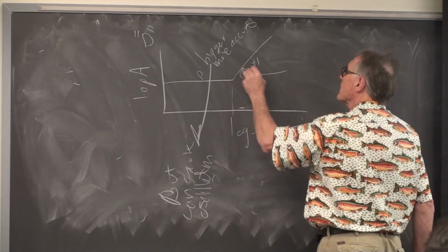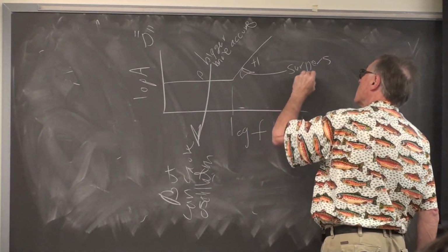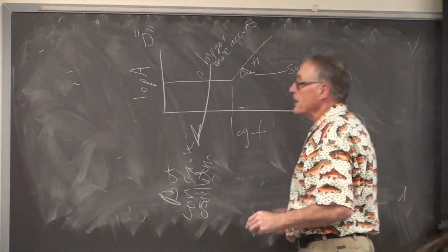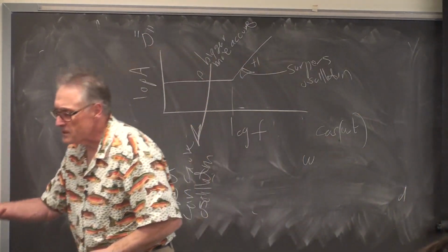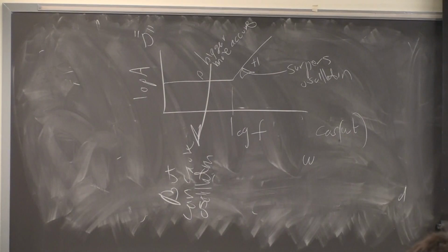This will help suppress oscillation, because it reduces the phase shift at high frequency, and therefore gets the system away from minus 180 degrees.